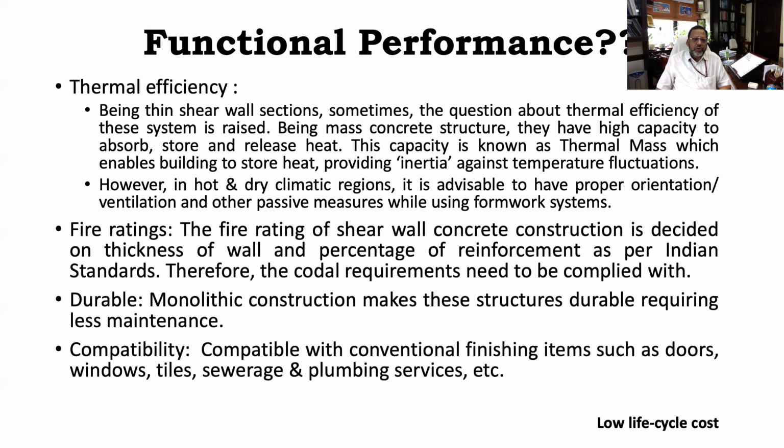And another thing I want to add here is that because the majority of regions in India are hot and dry climatic regions, it is always advisable to adopt passive measures for thermal comfort, to have proper orientation and ventilation in the project or the building where you are working. Also, sometimes it is advisable to have proper shading of the building by planting trees and shrubs, etc. Also, sometimes paint with a good SRI, solar reflectance index, helps in enhancing thermal comfort.